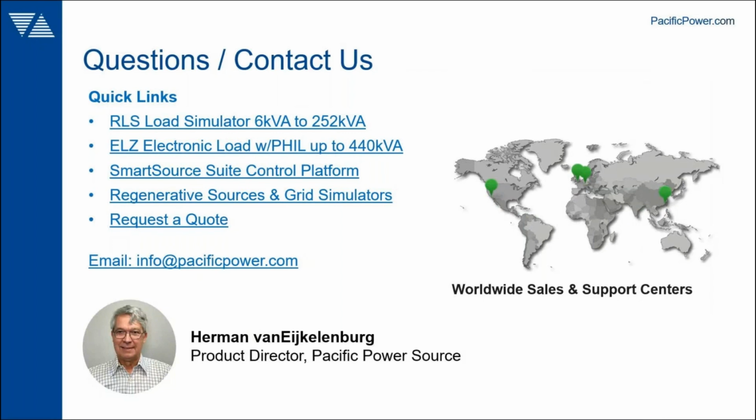In the US, it would probably be 208 volts or 480 volts three phase, or a single phase 230 volts or 120 volts, and then connect that to a one or three phase electronic load and load it up that way. So as long as it's a voltage source and you put the load into current or power mode, you can program what you want on the load side and draw whatever current and power you'd like to draw out of that supply that you're using to test.